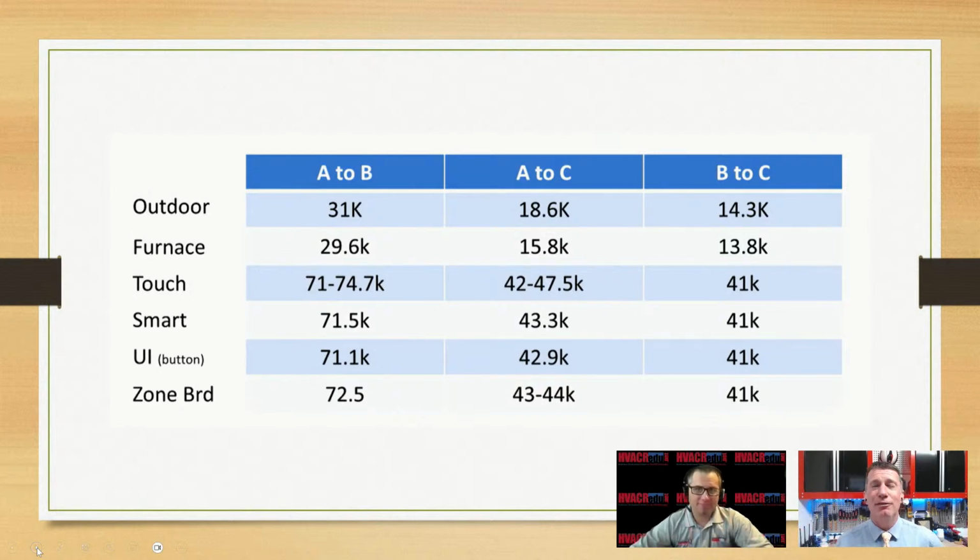So this manufacturer goes deep enough to say, after you've powered everything down and given the capacitors enough time to drain their voltage, you can disconnect these control wires, and we can tell you what the resistance of that board should be, so that you know if your DC power supply is actually good or not.